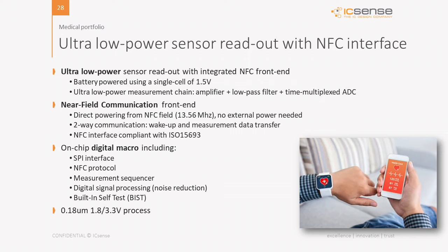And we were also able to set up a two-way communication so that either the wake up and the measurement data transfer can be used for that. And the NFC interface is also compliant with ISO 15693. Next to that, the chip also contains a lot of on-chip digital processing, like an SPI interface and the protocol itself, a measurement sequencer, and a lot of built-in self-test protocols.